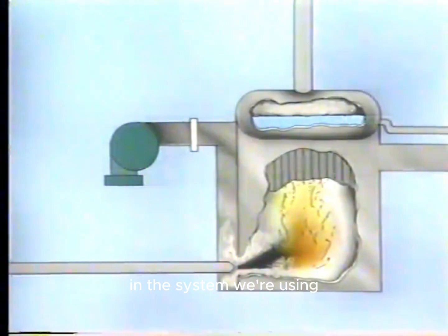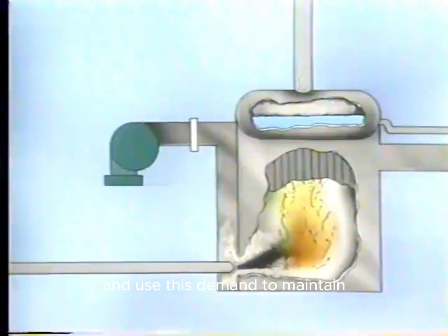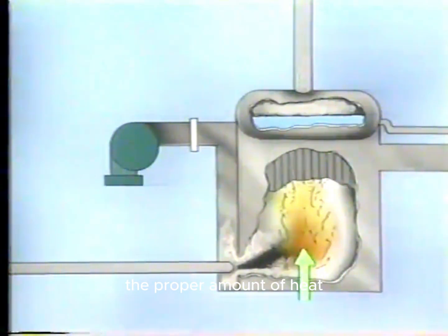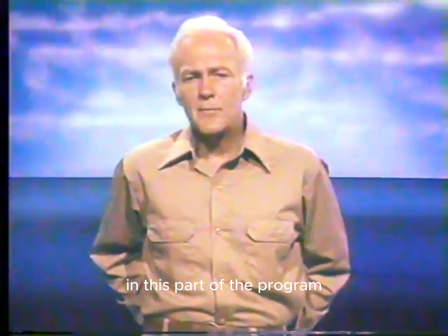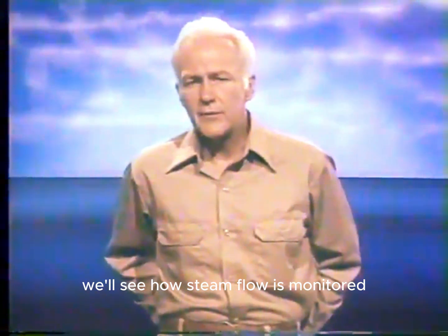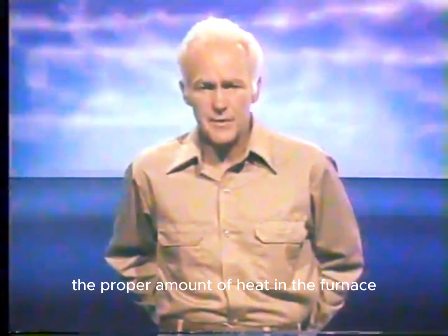In the system we're using, it's possible to monitor the steam flow out of the boiler to determine plant demand and use this demand to maintain the proper amount of heat in the boiler furnace and the proper water level in the boiler drum. In this part of the program, we'll see how steam flow is monitored and used to maintain the proper amount of heat in the furnace.